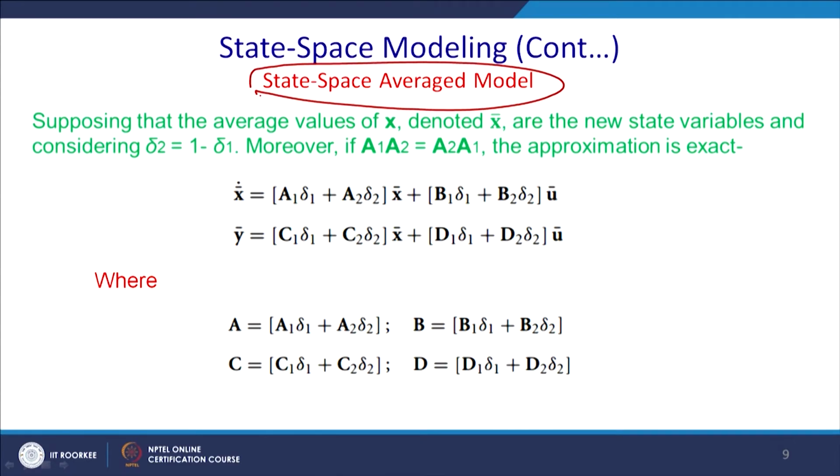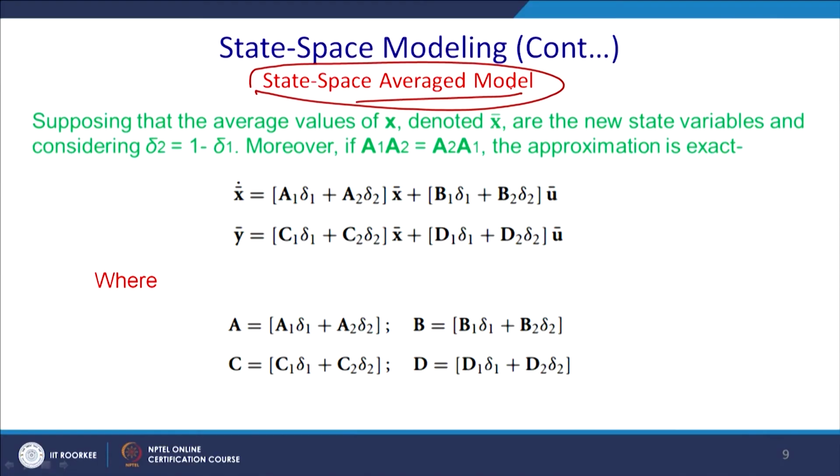Now, we wanted to have something called an average state space model. Some phenomena we require to observe, and that is possible because it is switching. So, once we say that it is average, we are not capturing any phenomena at the rate of the switching frequency. We will be capturing basically 1/10 of the switching frequency, and we will analyze the stability of the system. So, then we will say that it is an average model.